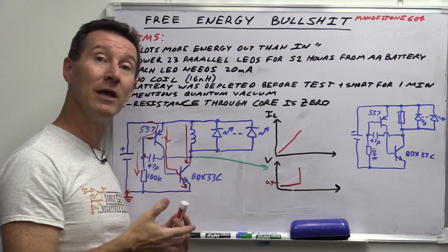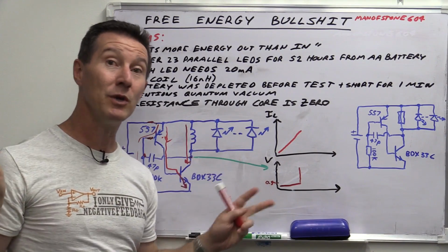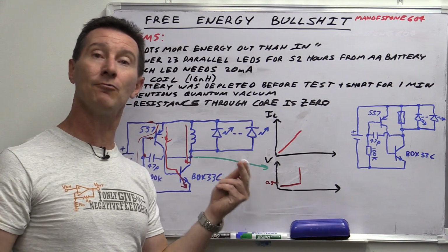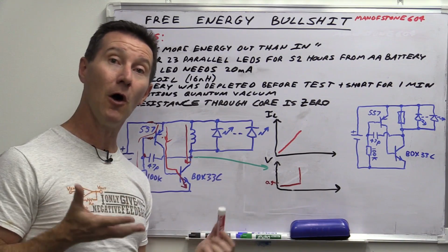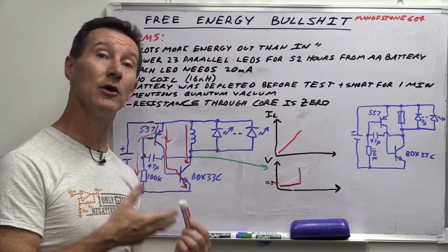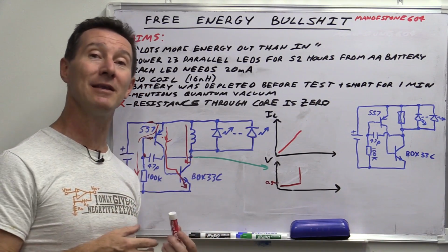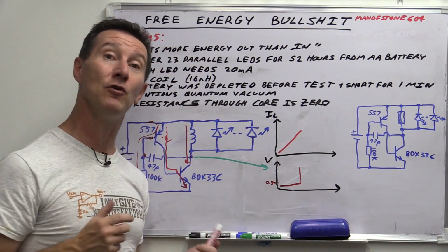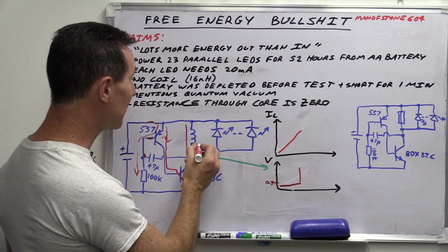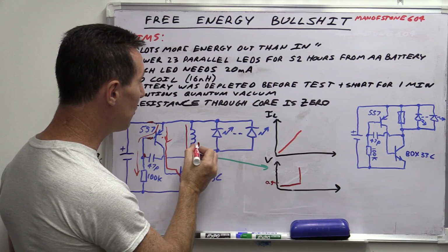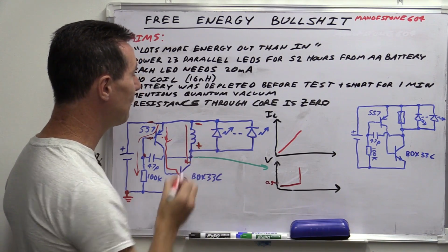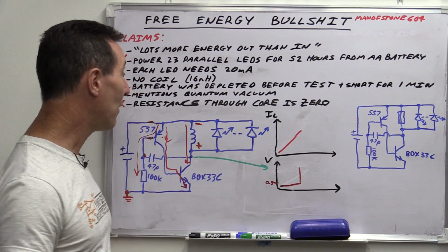So our voltage has to, it's like switching off a relay coil, for example. You're told to put a reverse diode across the relay coil. Why? When you switch off the coil, the collapsing magnetic field generates a large reverse voltage. So we've actually got a huge reverse voltage, positive, negative, like that. And what does that do?